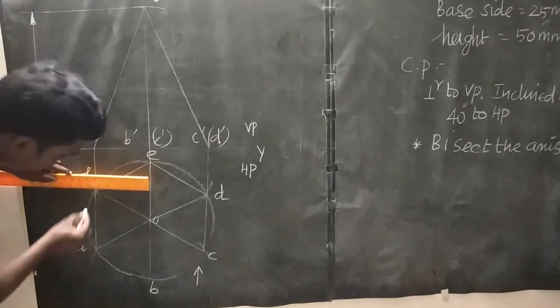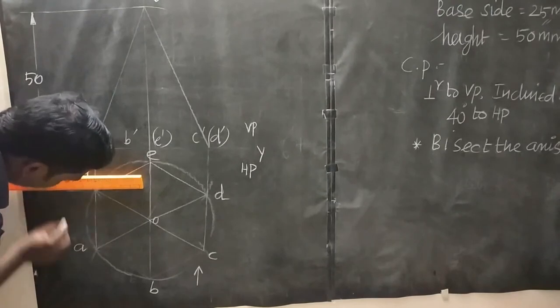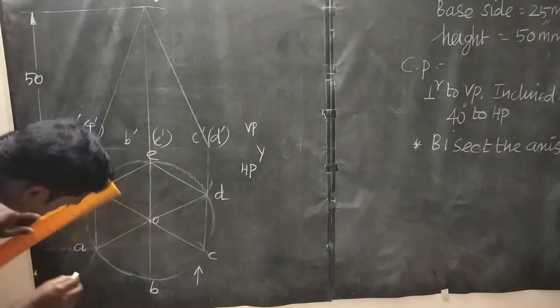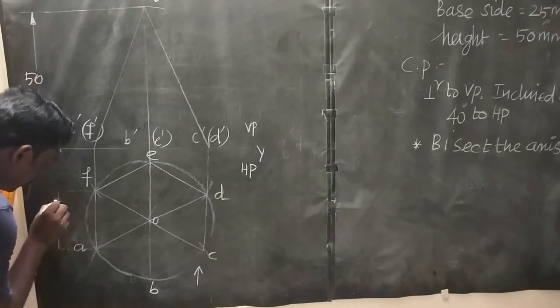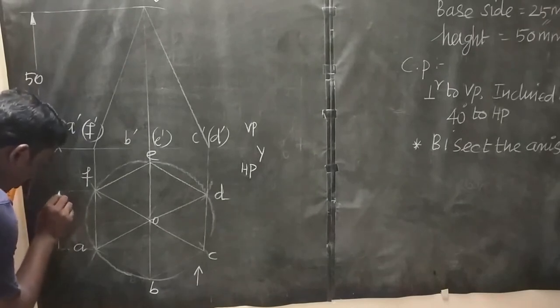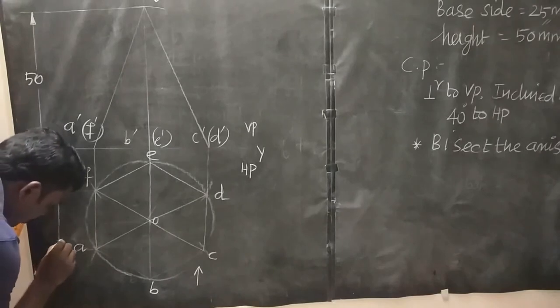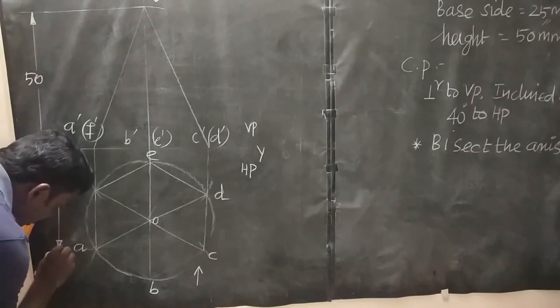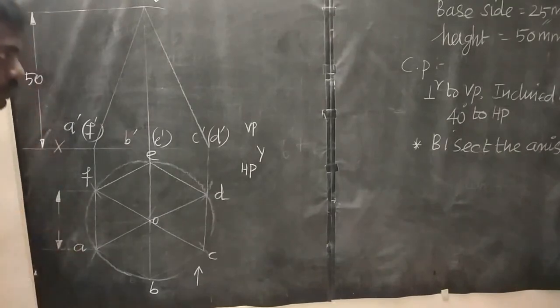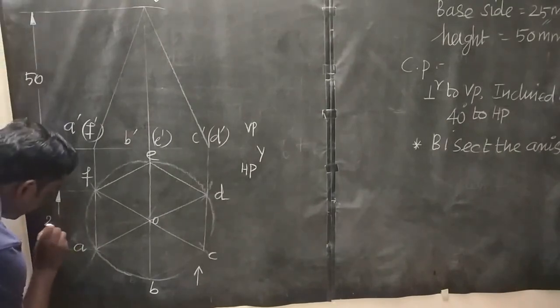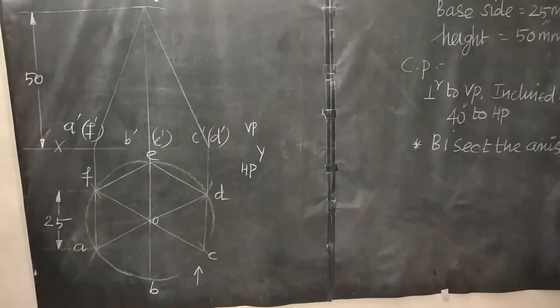That's all. Then from point F, draw a horizontal line. From point A, draw a horizontal line. Then draw a dimension line. Then draw the arrow with the 3:1 ratio. Okay, always follow this condition. Then erase the middle part. Then insert your dimension value as 25 mm. So up to this you will get 8 marks. If you draw this neatly, surely you will get 8 marks.